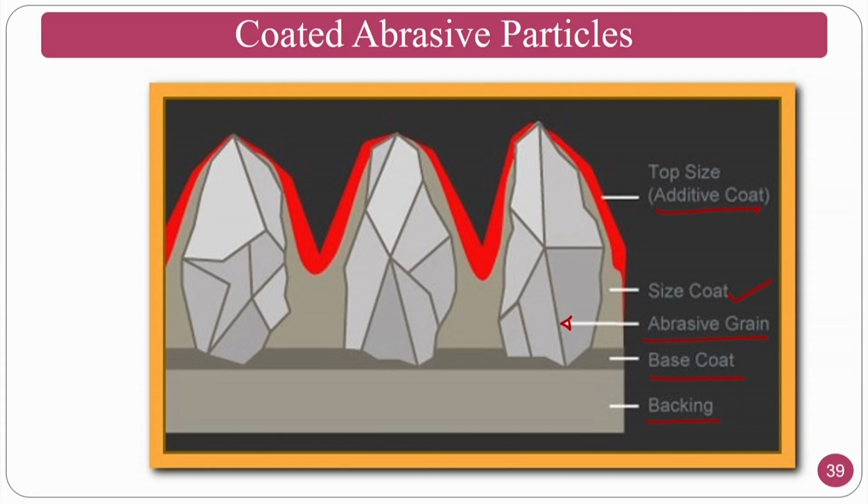Whenever you talk about the magnetorheological finishing process or polymer rheological abrasive finishing processes, these are abrasive finishing processes. In these processes, if you need perfect bonding between the rheological additives and the abrasive particles, you can vary that bonding strength by functionalizers. You can coat, or in a ball milling operation you just put the functionalizer and mix it, or use ultrasonication, or many techniques to functionalize it, or you can coat it. These are called coated abrasive particles.